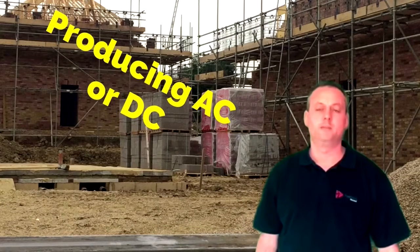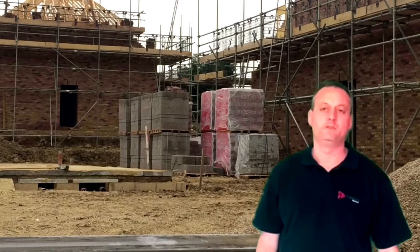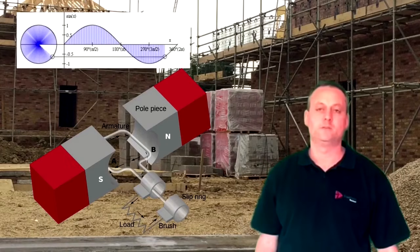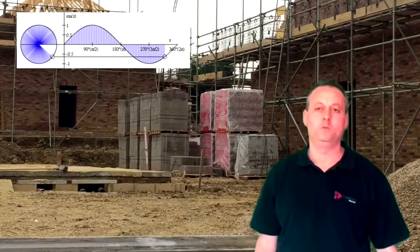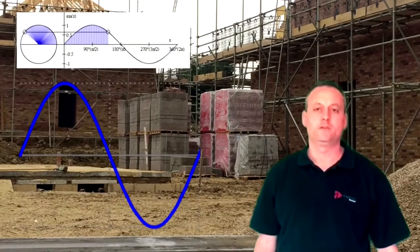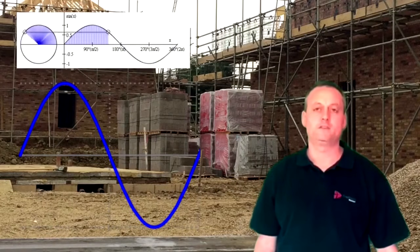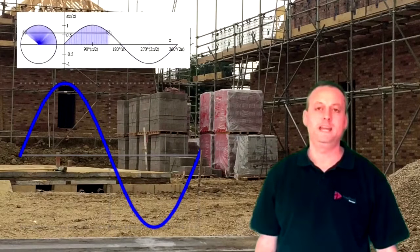Next thing we looked at was single loop alternators. In other words, a conductor being rotated in a magnetic field, and whether we could produce AC or DC from rotating that conductor within a magnetic field. And we saw if we connected that single loop of wire to slip rings and rotated it 360 degrees through a magnetic field, we saw how we produced an AC waveform, in other words, a sine wave. One complete revolution of 360 degrees will give you a sine wave with a peak in the positive half of the cycle and a peak in the negative half of the cycle. One complete revolution is also called a period.